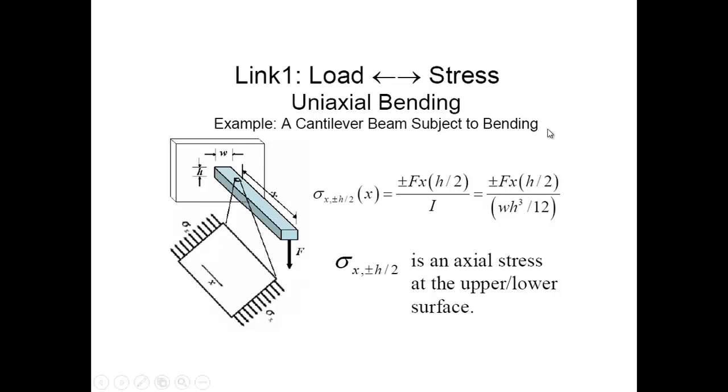You still remember from solid mechanics how you find the bending stress, right? It's equal to plus or minus My over I. If you still remember, you calculate the moment from here, and this is your y, which is the distance from the neutral axis, and this is your I, which is the central moment of inertia. So what they are trying to say here.